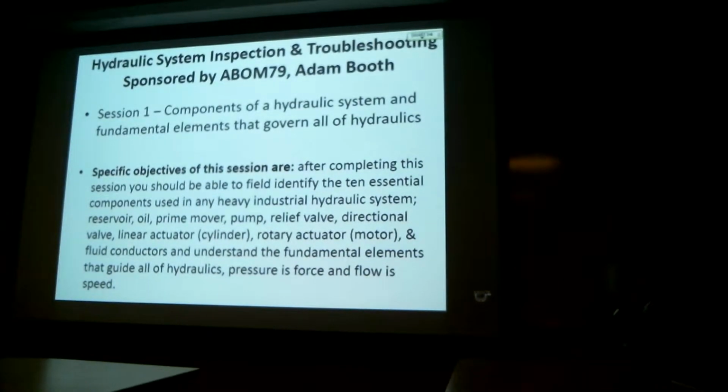And understand the fundamental elements that guide all of hydraulics. So if you walk away with understanding that pressure is force and flow is speed, you'll understand a lot more than most folks do when they're out there trying to troubleshoot hydraulic problems.